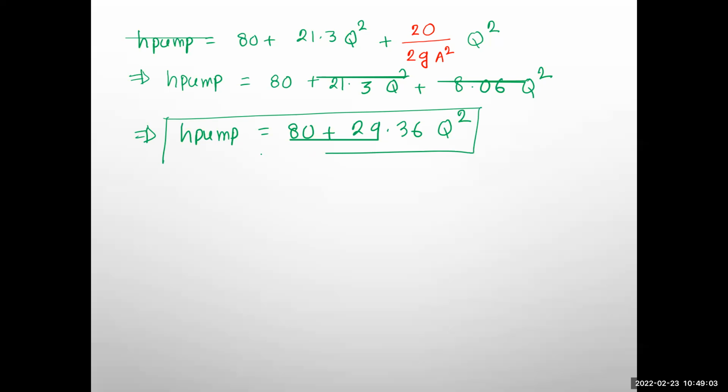Okay, so is that a system curve or a pump characteristics curve we developed here? It's the system curve because you are using all the pipe diameter and length from your system here, right? Okay. Once you have the system curve, what should be the next step? You have the curve, but you need to get the operating point. So you need to build the table, another curve. Yes, at the same time, you need to plot that, right?